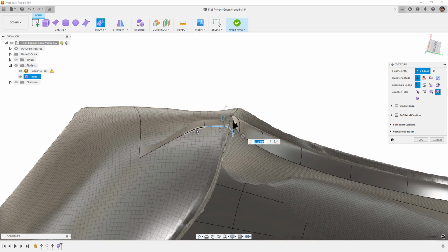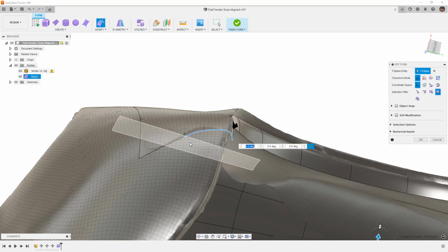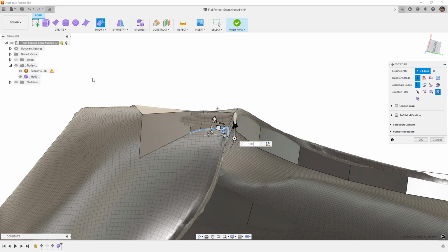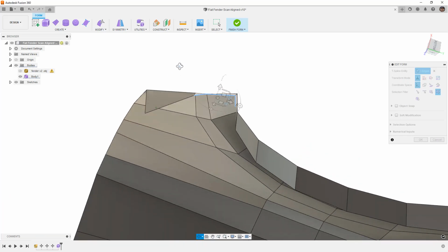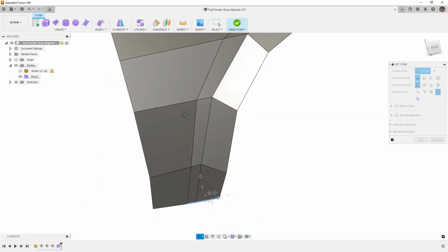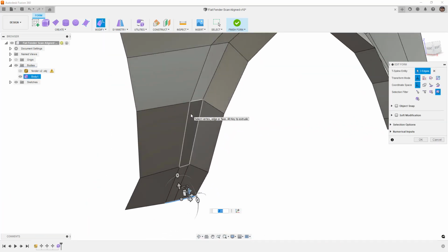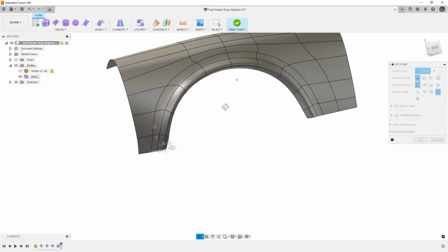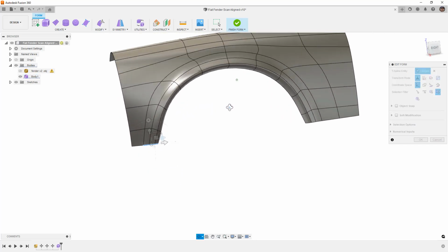I'm going to grab all of these, probably leave that vertex there, and just pull it back in just a little bit. And this is a little bit too far in, so I'm going to reset the pivot point. I'm going to put it over here. Then I'm going to scale this in this direction. Double check the box display to make sure that we aren't, again, producing bad geometry. And that looks pretty good. Smooth display. Everything looks pretty good so far.